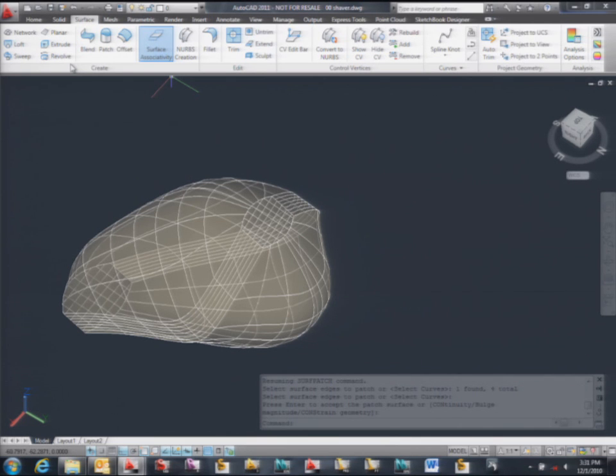So that's it. If you extrude a rectangle from the surface tab, it's just the sides. If you extrude it from the solid tab and it's really closed, it's a box. So you just may want to be a little careful where you call the command from. In the past, I would normally create the box as a solid because it was the only thing I could do, and then explode it and remove the top and the bottom. So again, 3 more steps or 4 more steps.